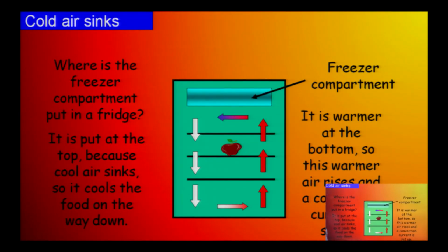So where is the freezer compartment put in the fridge? See, this is the freezer. The hot thing is here, and the cold air coming from the freezer compartment is coming down, taking the heat away, and the hot air is rising. The freezer base is very chilled, and this hot air, while in contact with these chilled pipes, gets cooled down, and this is heavy or dense, this is light. So the same thing, the convective currents are set up here.